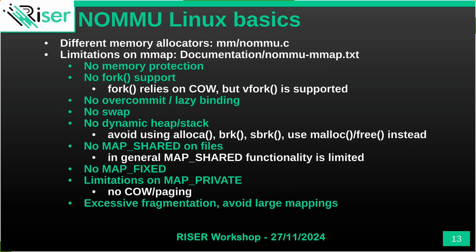So you get a few limitations on no-MMU Linux. You don't have fork. You don't have copy-on-write. You don't have memory protections. Okay, it's for testing, it makes sense, but your software will have some limitations. You're not going to use exactly the same stuff you'll be using in the MMU scenario. You need to know about this so that you have an idea of the test coverage, like what things you'll be using.